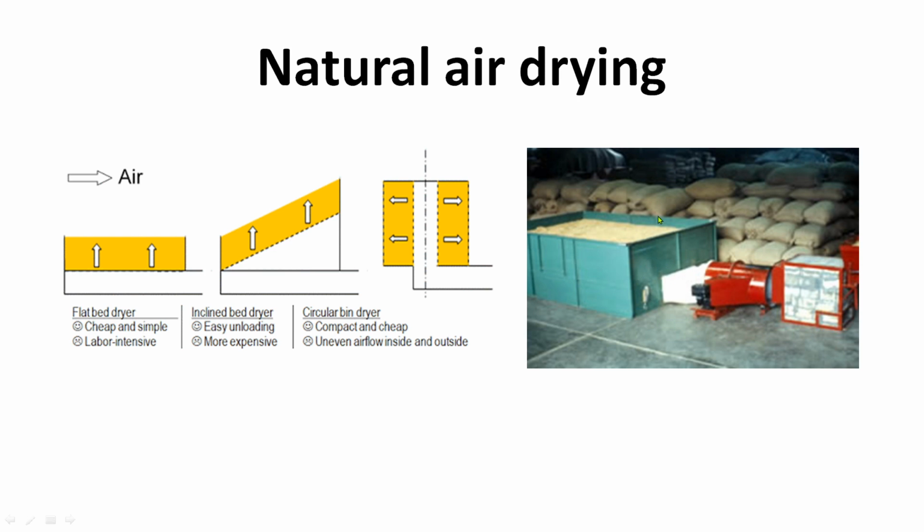There is also a great risk during winter and rainy season, as the air present in the external environment has high relative humidity. If we blow air with high moisture content, it will increase the moisture content instead of decreasing the moisture content in the seed.